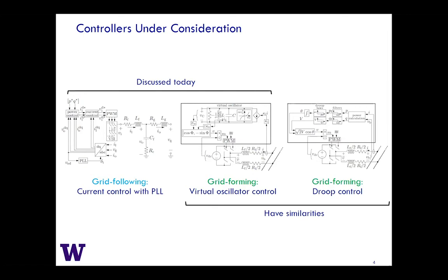If you look at its quasi-steady state behavior, it has droop-like functions embedded inside of it. So it is a lot like a nonlinear droop controller. We did that so that people wouldn't be so scared of it when they saw it. It really shows you that there is an underlying functionality that these grid forming controllers have. It's these droop-like functions that allow them to function.